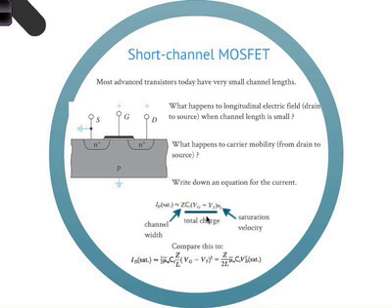So it's a very similar situation we had in the JFET. In other words, the transconductance is independent of the gate voltage. It's a linear dependence as opposed to a square dependence. So when you model a short channel MOSFET, it looks very different than a long channel MOSFET.